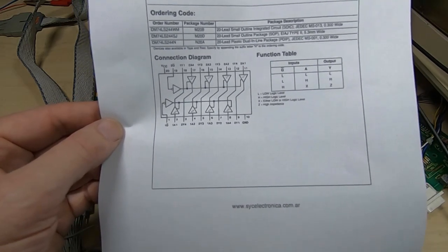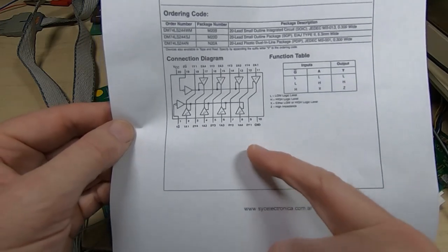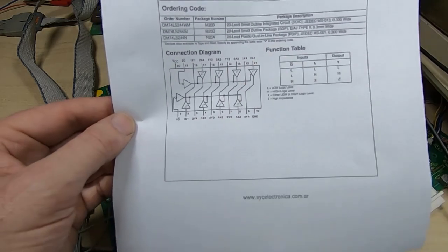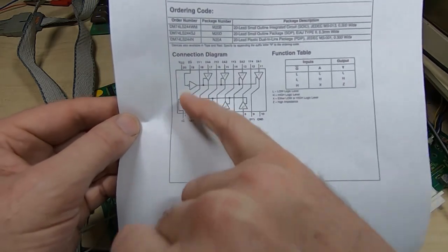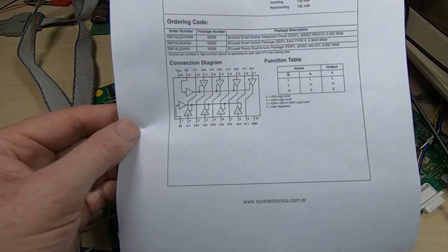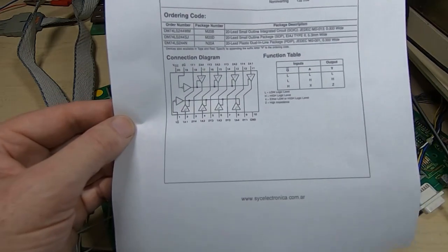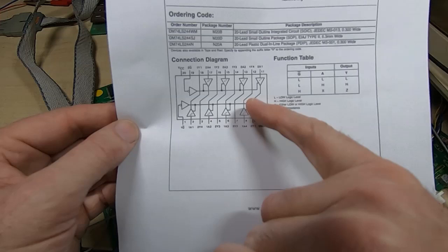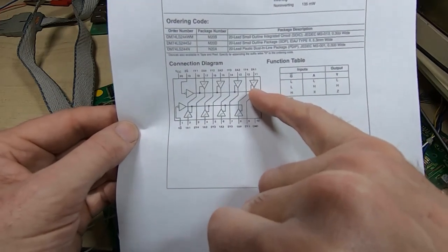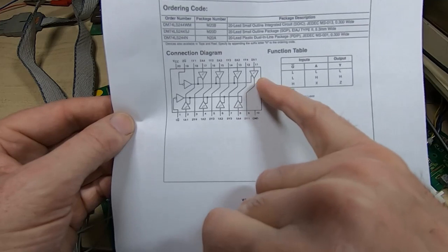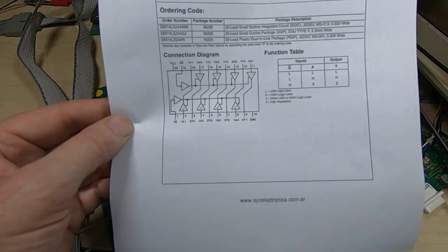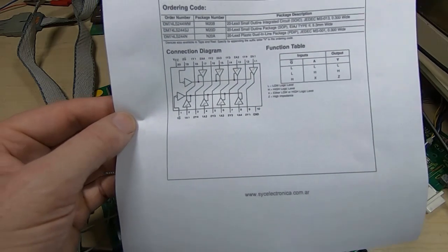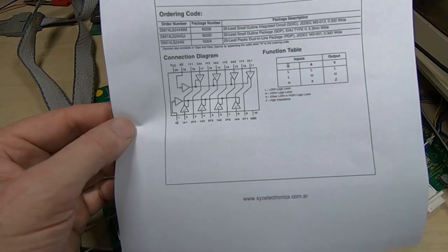So we'll look at the logic analyzer, and the thing to bear in mind with these devices is sometimes they are used to take advantage of the tri-state outputs, and other times the control lines are just hardwired to ground, in which case these are used just as permanent buffers that are on all the time. These can also be used to tidy up signals for increasing fan out. They've got Schmitt trigger inputs, so they do tend to be relatively immune to noise, or they might just be used for timing purposes to introduce a short delay.